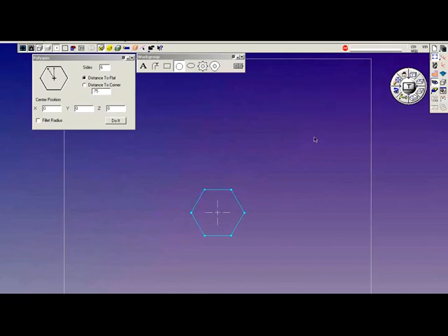Undo that. Another method for verifying geometry, one that I prefer to use, is the mouse tool. Right mouse click on the geometry, go to mouse position, and in mouse position, you can measure locations and distances using the cursor.